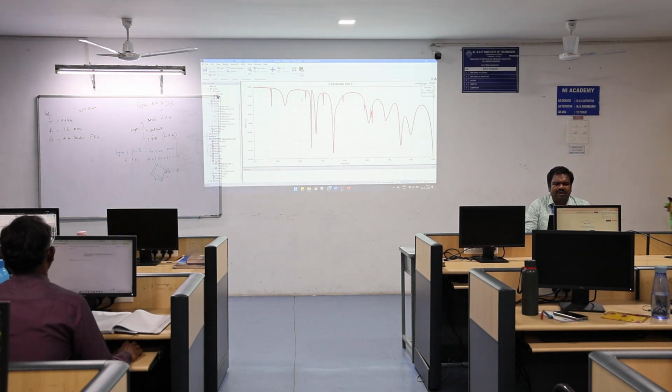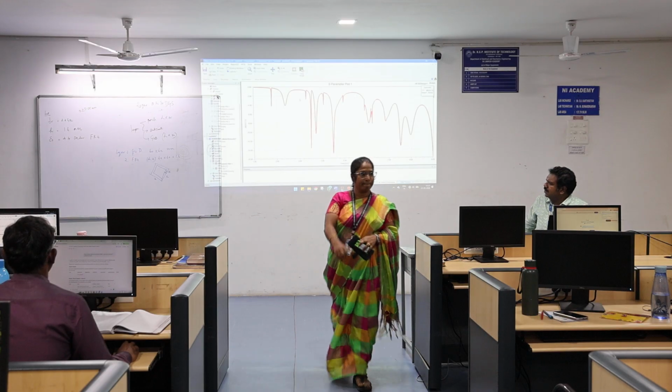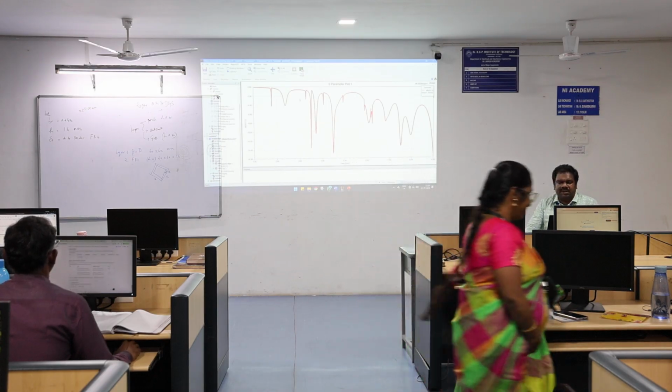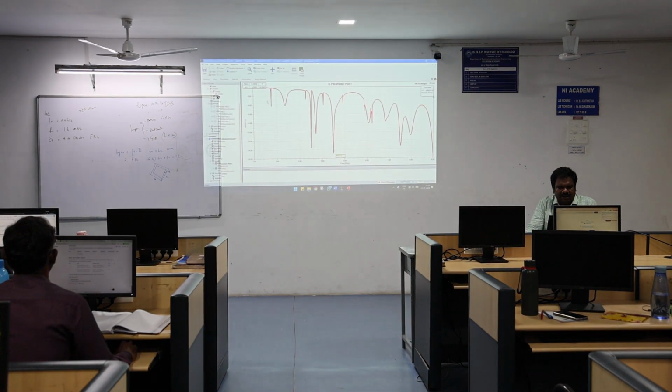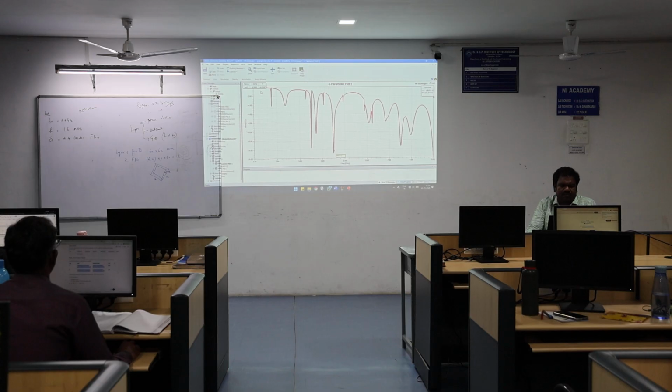These results give us the lower cutoff frequency, higher cutoff frequency, and bandwidth. For example, here the marker value is called a, at 4.5 gigahertz, and minus 14.856 dB is the resonant frequency. We are getting the lower cutoff frequency and the higher cutoff frequency at the minus 3 dB level. The span between the lower and higher represents the bandwidth.